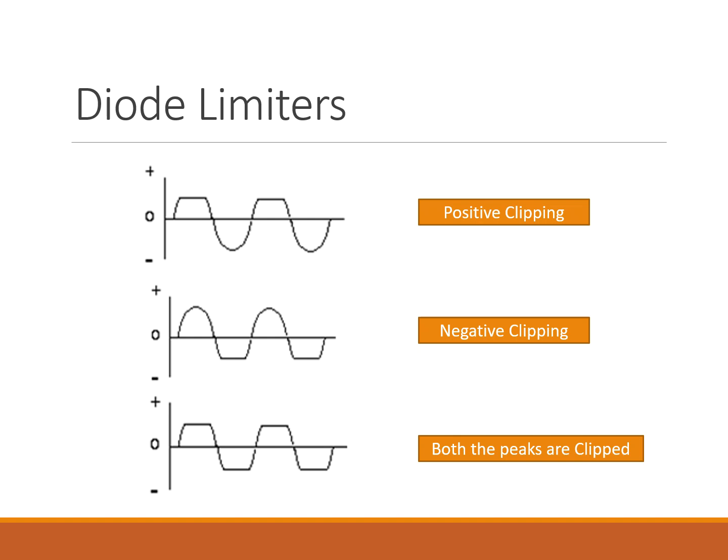Now let's go into negative clipping. What happens with negative clipping? This time the diode is flipped. We just turn it the other way. It clips the negative half of the waveform when it falls below 0 volts in this case, or some set reference. The output is that only the positive side of the waveform passes. The negative portions are removed, or flattened, just like the reverse of the first one. Where do we use this? Well, this would be used in cases where you need to block reverse current or you want to shape an audio signal.